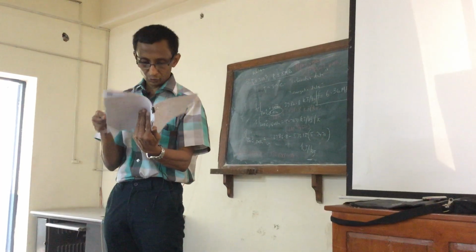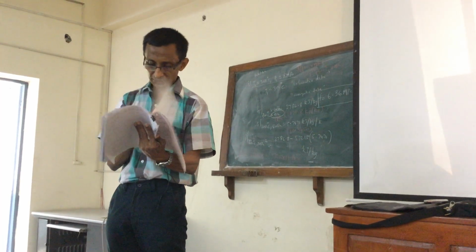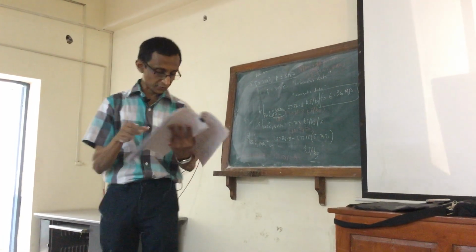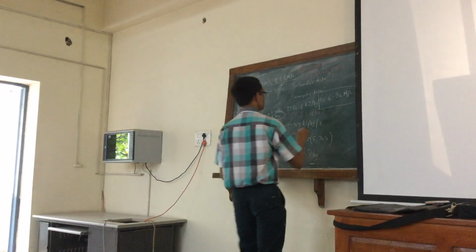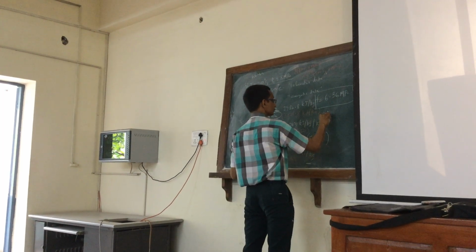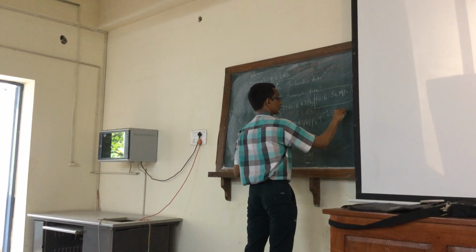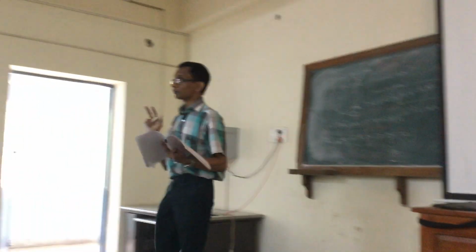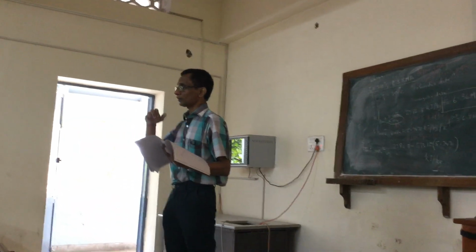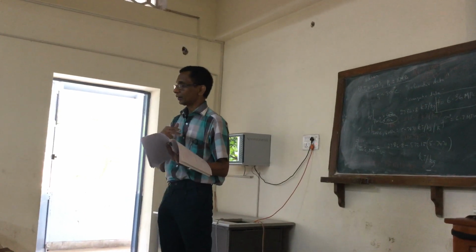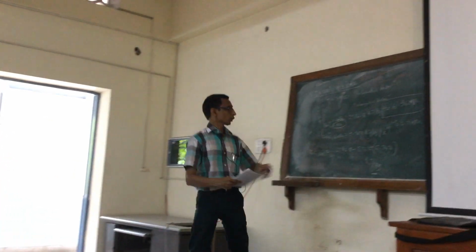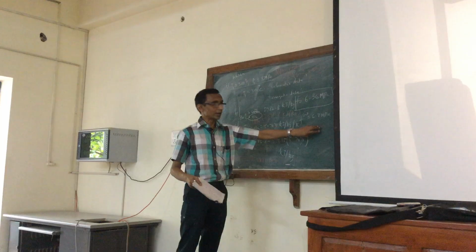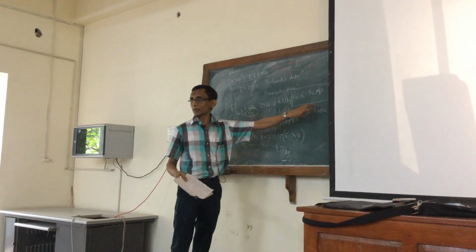And that turns out to be, I hope these answers are here, 6.7 megapascal. So even if the fugacity has increased, what is crucial is to look at F over P. You will see that F over P has slightly further reduced, because this has been divided by 8.6, while that was divided by 8.